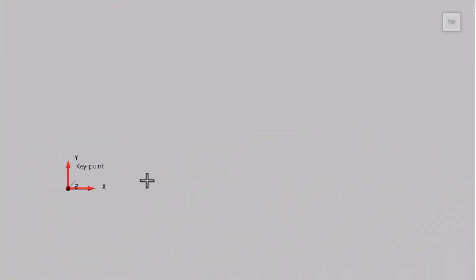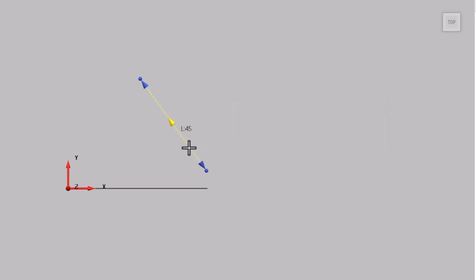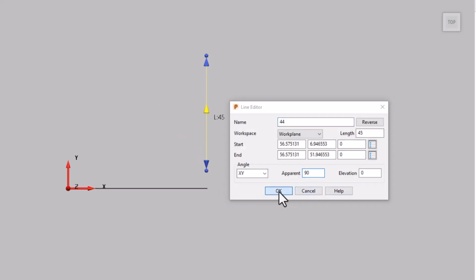Let's take one more scenario. You want to draw a horizontal and a vertical line, but your sketch turns out tilted. In PowerShape, you will either have to delete and redraw the lines or manually set the angle to 0 and 90 degrees and then realign the endpoints.